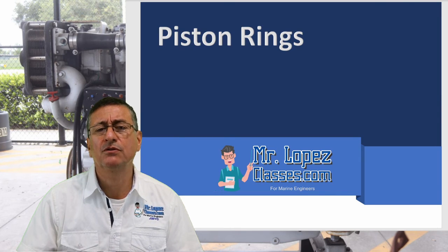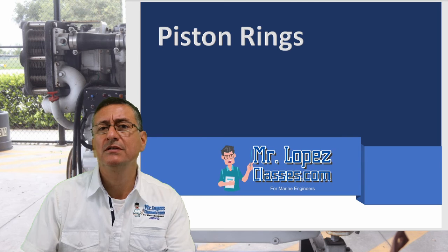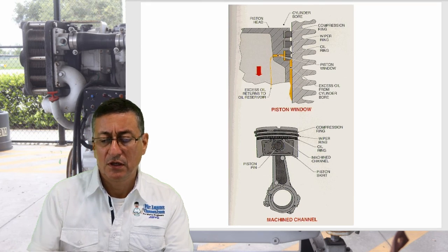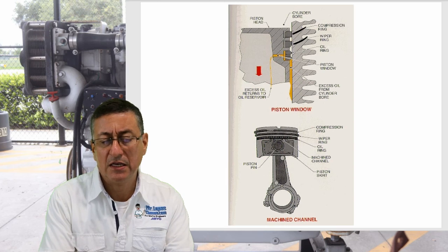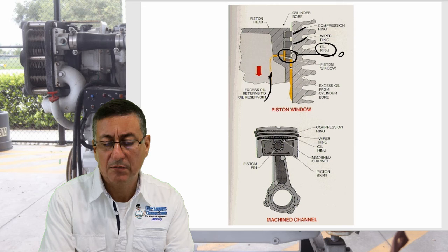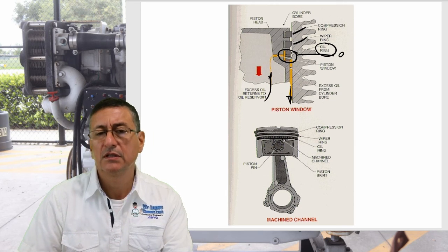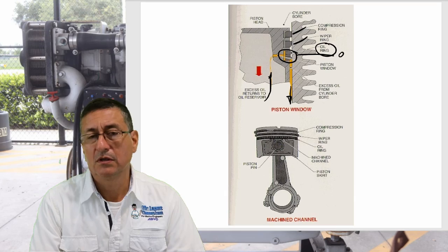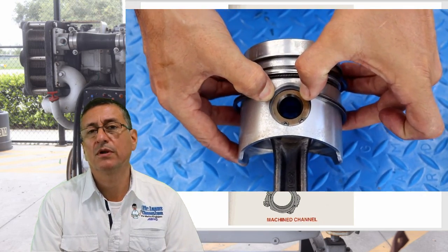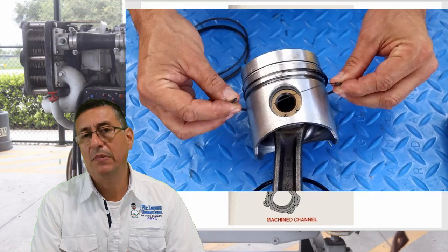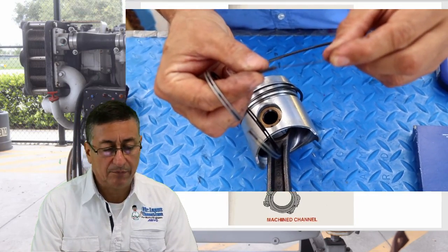And now we are going to talk about the piston rings. There are 3 types of piston rings. Compression rings are located on top. This one and these ones are compression rings, and this one, the ring located in the third groove, is an oil controller ring, and the oil enters over there, penetrates through the hole and returns into the bottom. This is the path of circulation of oil, because the oil controller ring is hollow. Like the oil controller ring that you have on the screen right now, it is hollow, and the oil controller ring allows the oil to pass and return into the oil pan.